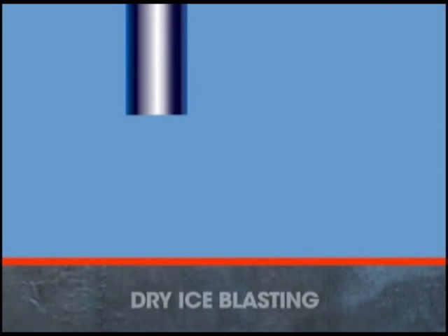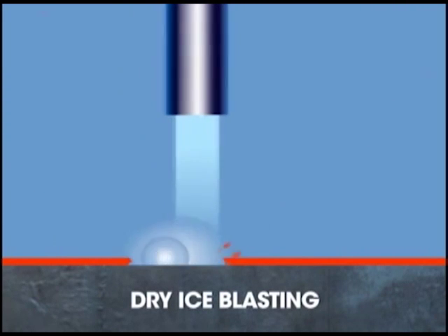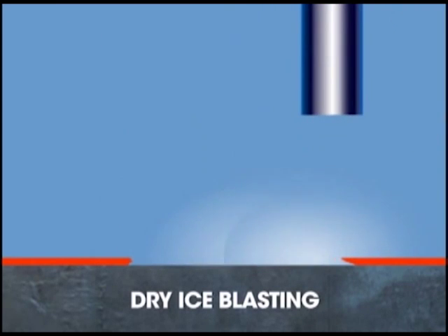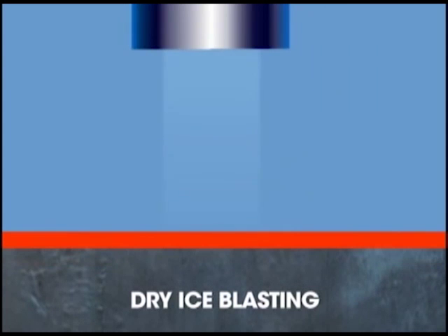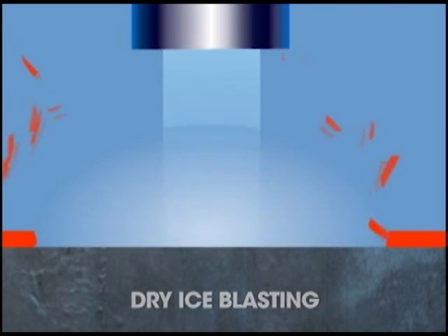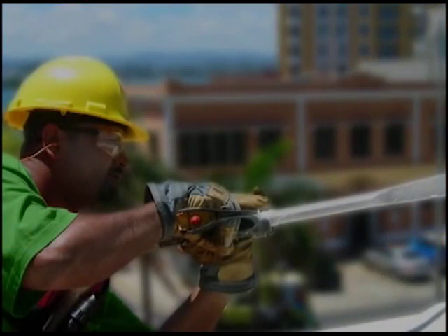Dry ice, on the other hand, disappears as it cleans and will not alter most industrial substrates. On successful cleaning applications, the dry ice pierces the contaminant, but sublimates upon striking the underlying substrate. The resulting expansion of the carbon dioxide gas actually lifts the contaminant off from the inside out. The dry ice then disappears without damaging the targeted surface, and without creating grit entrapment issues.